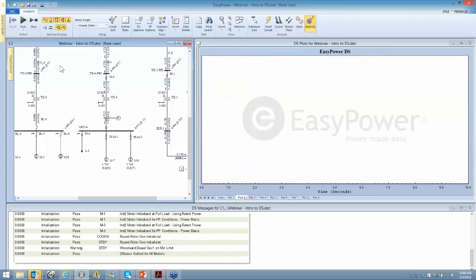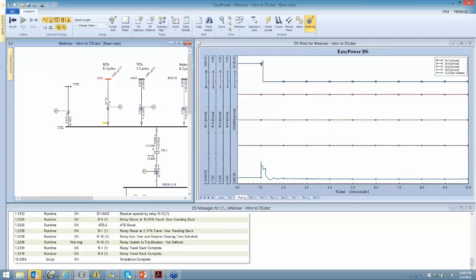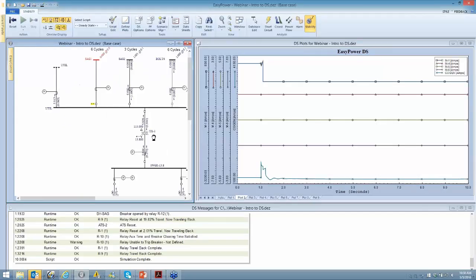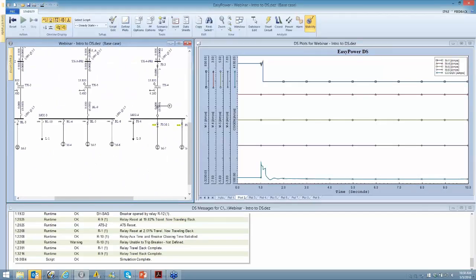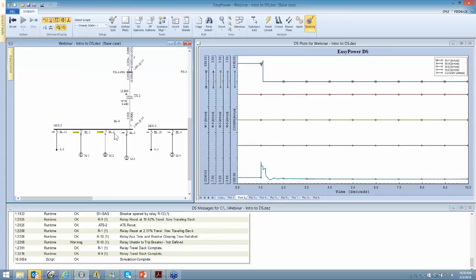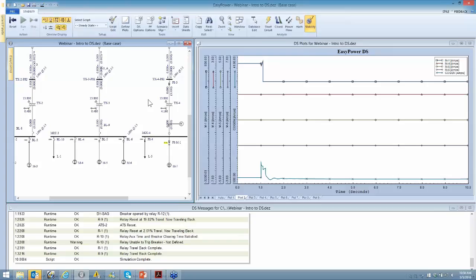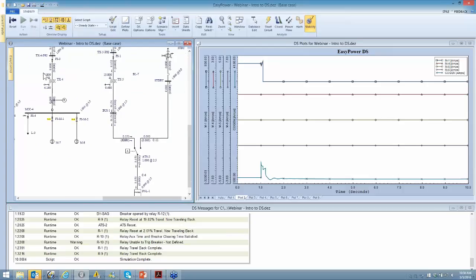So let's try a 6-cycle sag by faulting this other bus. And again, now you can see the fault lasts much longer, and if we look at our end results, we lost those same 2, and we pretty much lost all of our loads on the motor side. So again, we're examining how the system responds to sags, which is not that relevant to strictly a short circuit analysis.